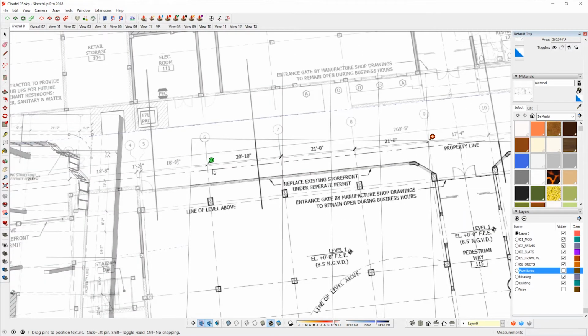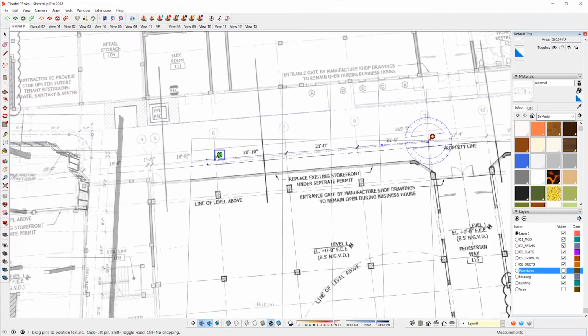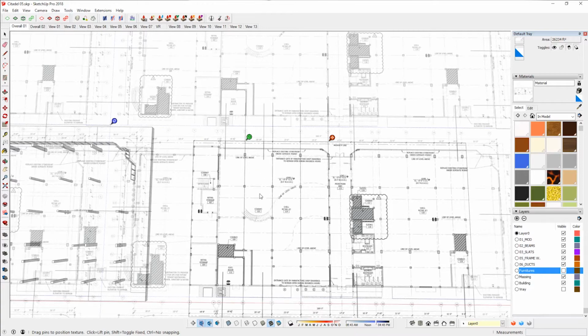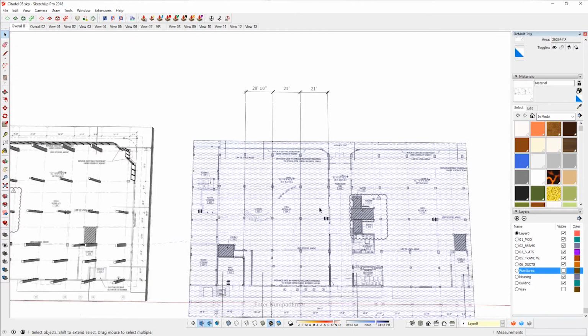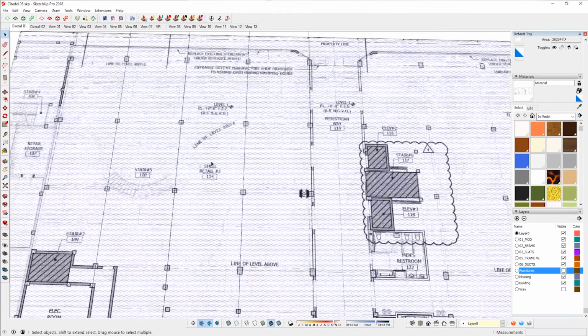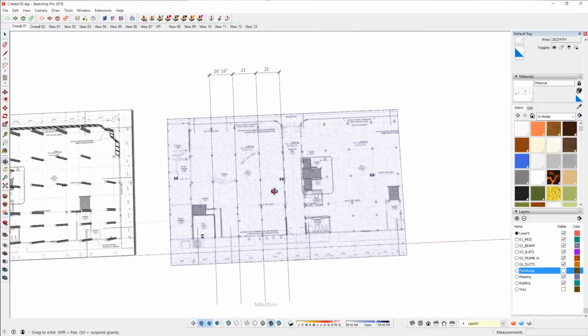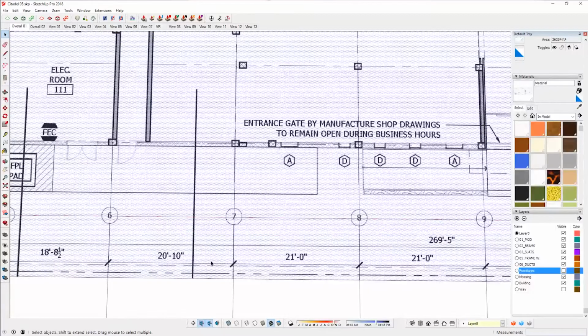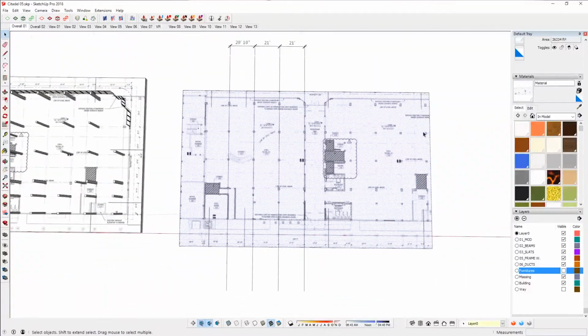So that corner there and that corner there, and then I'm just going to drag that back onto the grid line that I initially drew, and that should all be in scale properly. So for the best result, you have to do the furthest corners possible, then you will be more accurate. However, since you've got some dimensions down anyways, it should all be scaled properly, and this is how you would do it. Okay, so here's another practical application of this workflow.